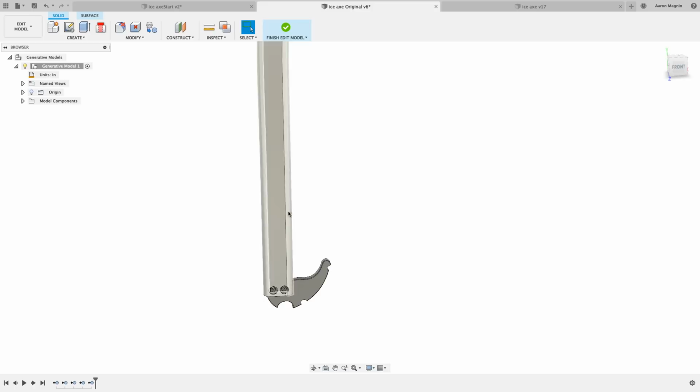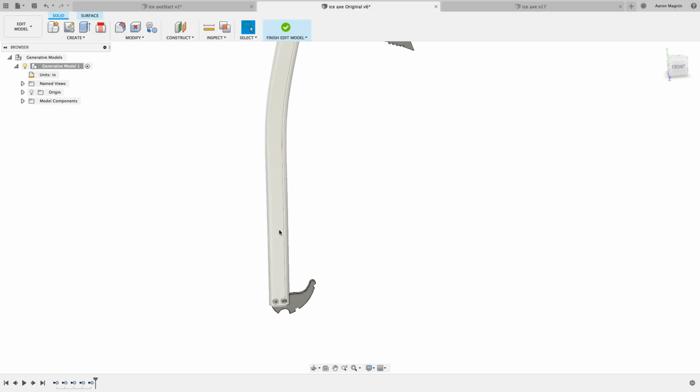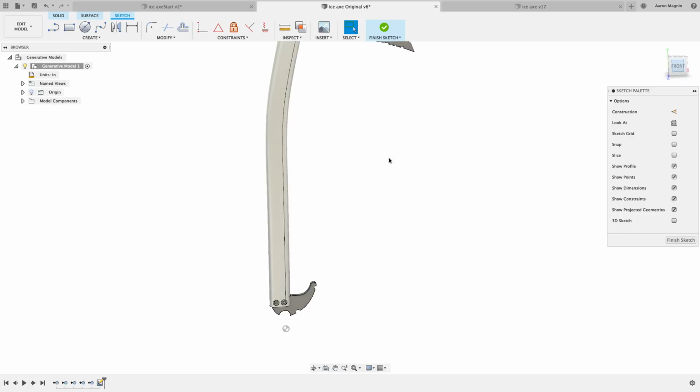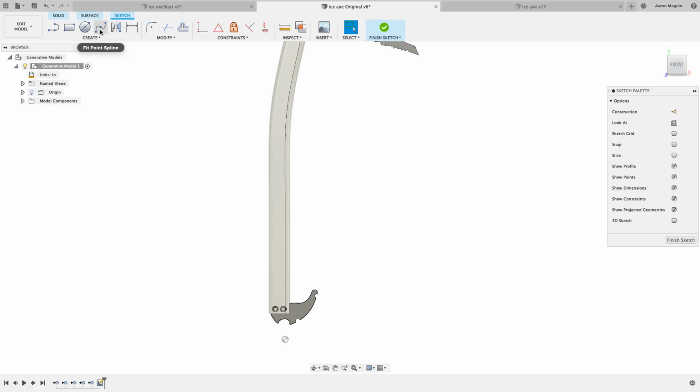And then I want to start to split a region from the existing handle, which I'll use to define a preserve area, right? So I'll create a sketch, and I'm just looking for a flat face. I could use the plane that's here. I could use the face on the front of this back piece there. And on this, I'm going to do maybe just some real simple lines. Like I'm going to draw a line across here, and I'll draw a line across here.